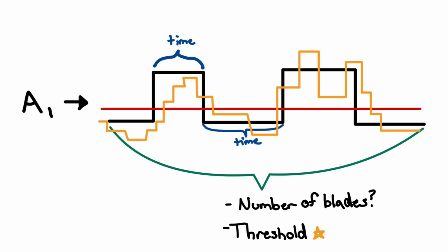Because there will be ambient IR in the room, we'll have to use the first 5 seconds to calibrate our device and find that minimum threshold for the up clock signal. Also, our up clock signal won't be that clean. There'll be steps in it, and so we'll have to use that threshold to define when we're above and below.